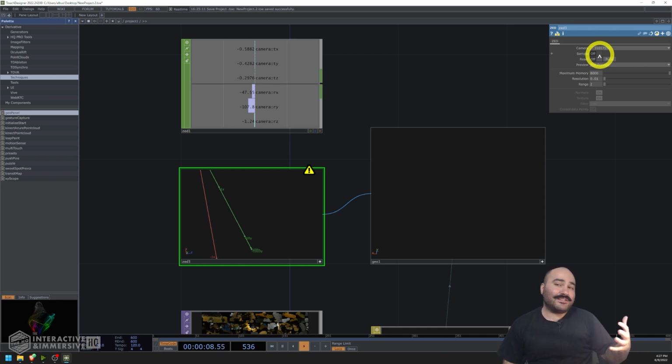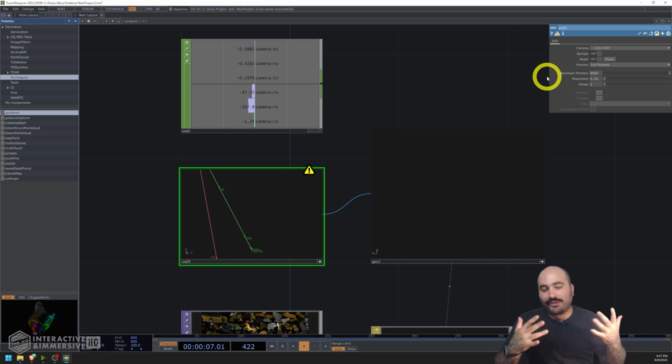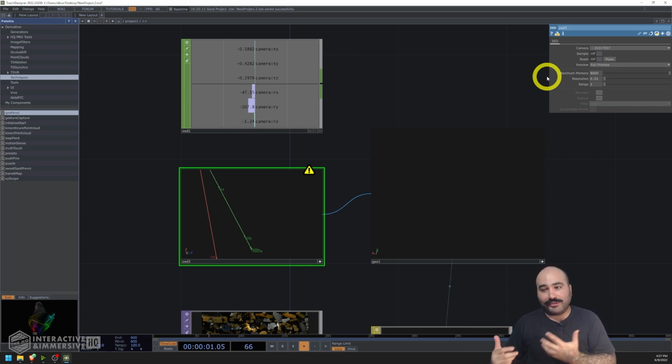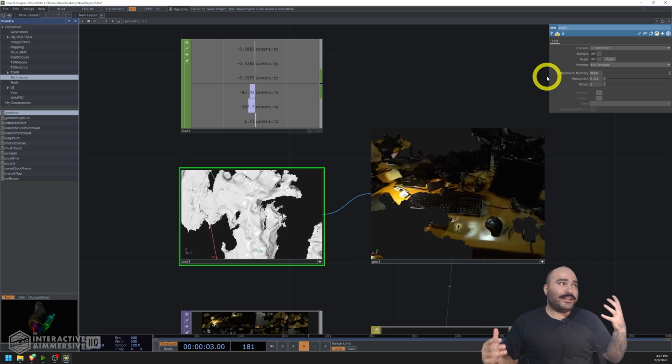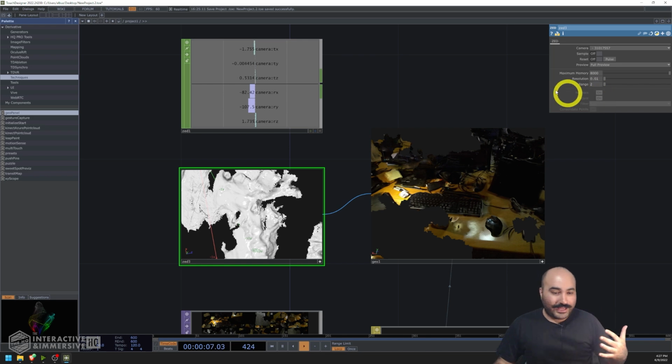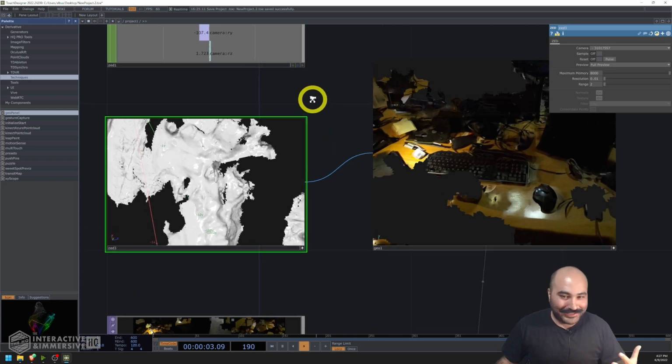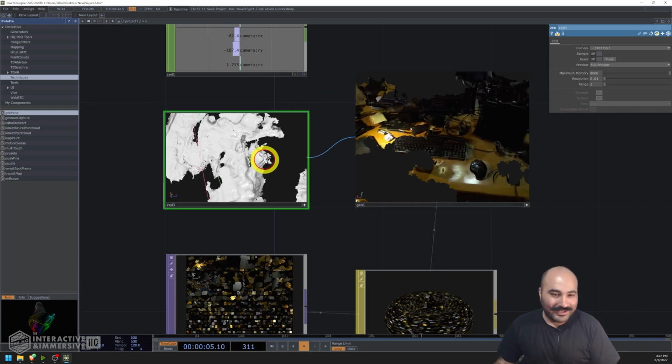It really is going to vary on what kind of resolution you have, how much filtering you have, the range you set. All of these things really play a part into what kind of mesh actually gets generated and comes out the other side. Especially in situations where maybe you don't need things like normals and textures, turning those off is going to help speed up the process. But we can see already, even with me not finishing my rambling, we have our 3D scan that's come back.